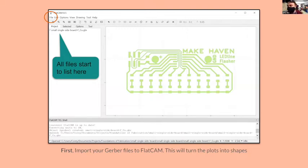Those Gerber files that we exported in KiCad or Eagle, all you do is import them into here, and from there it can take these designs and turn them into CNC G code. If you've been playing with the Shapeoko, think about designing something for the Shapeoko in a complex shape and then using Easel to make the G code that works with it. FlatCam is very much doing that, just on a super tiny scale. So this is going to make G code from a Gerber file. GBR is typically the file extension for a Gerber file.